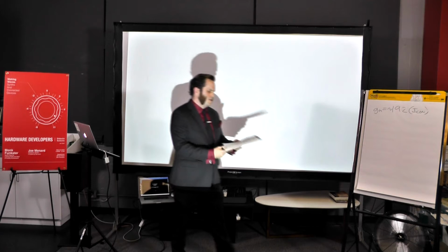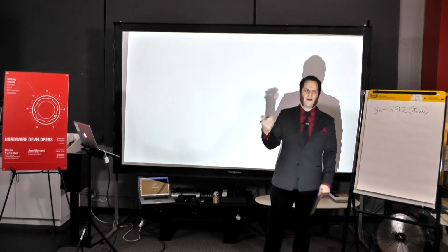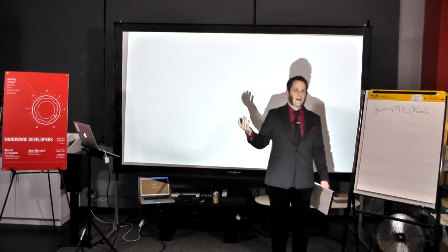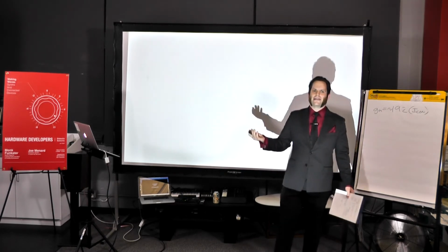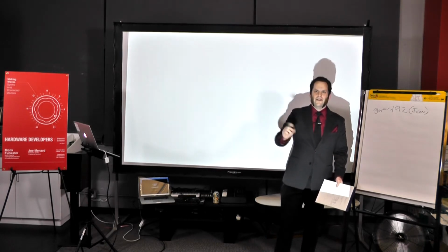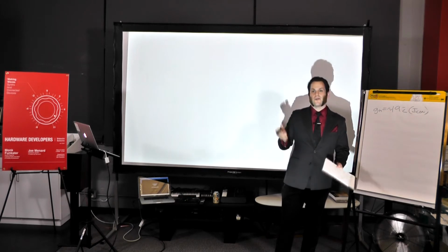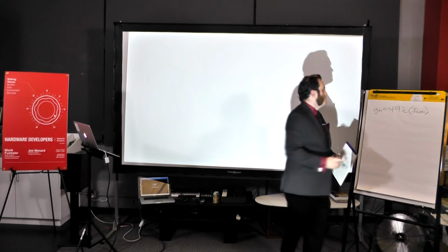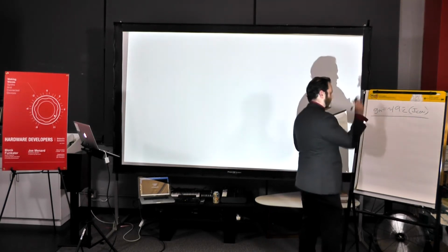We talked about building a VCA with an op amp. It's pretty straightforward. We have something that converts a voltage into a current for us, and we drive it into that I control pin of an OTA. It's pretty neat. Now we get to do the really fun stuff, which are voltage-controlled oscillators. We like voltage-controlled oscillators. Oscillators are pretty cool in general. You can turn a trim pot and have a 555 make some weird noises. That's great. 555s are cool and all, but you get like 1 octave of range. Boring. Anyways. So I talked about this magic equation, and I'm going to completely ignore that for now.